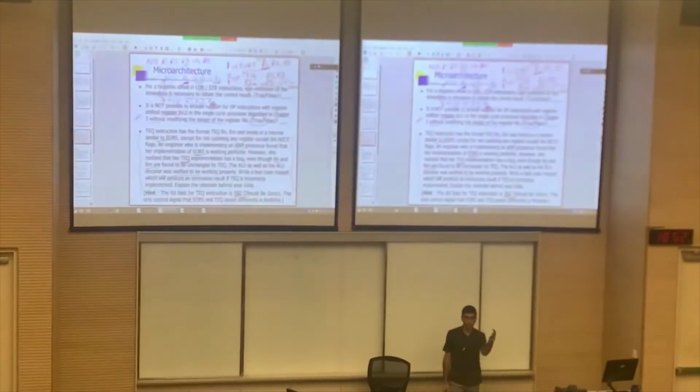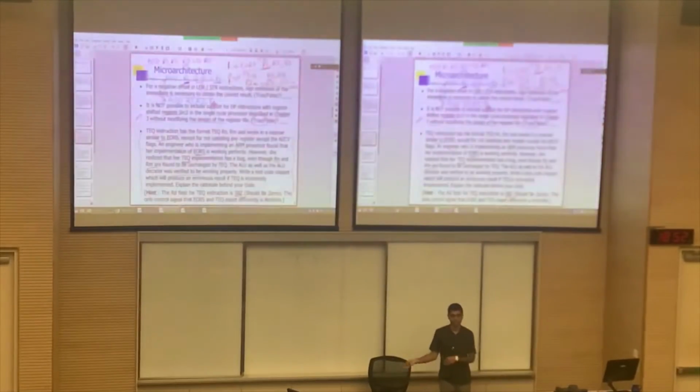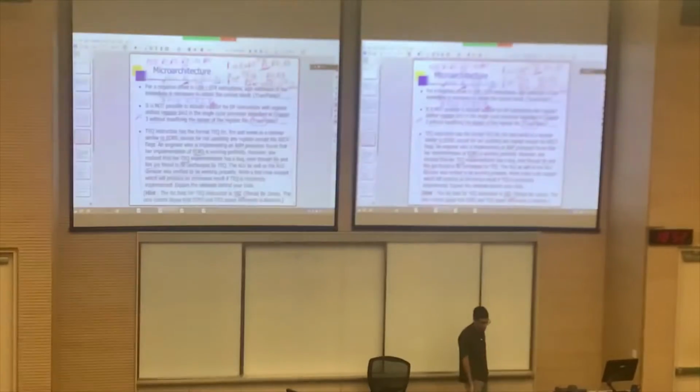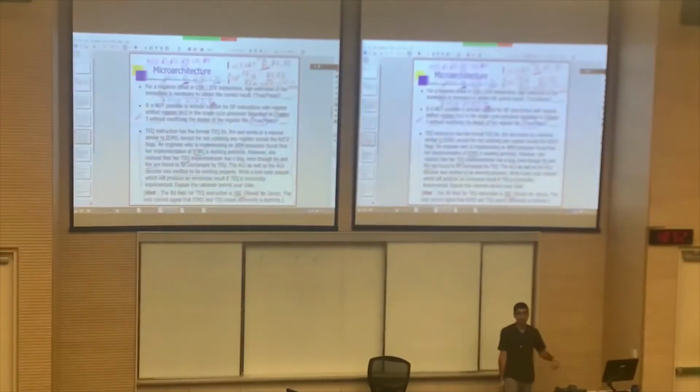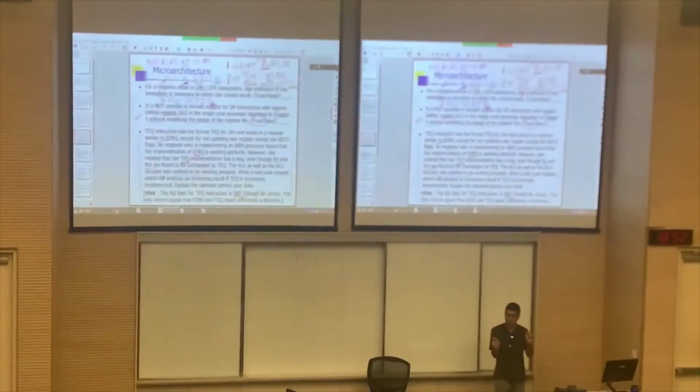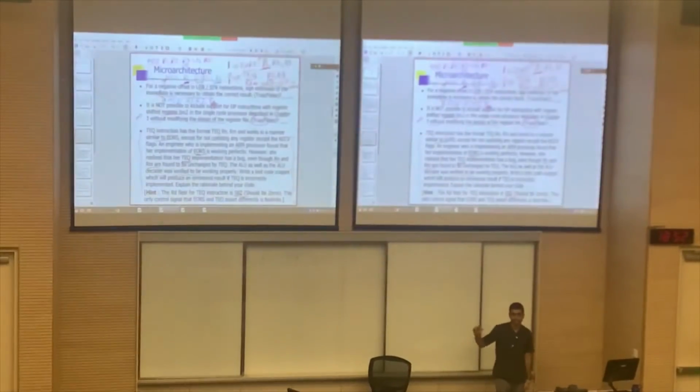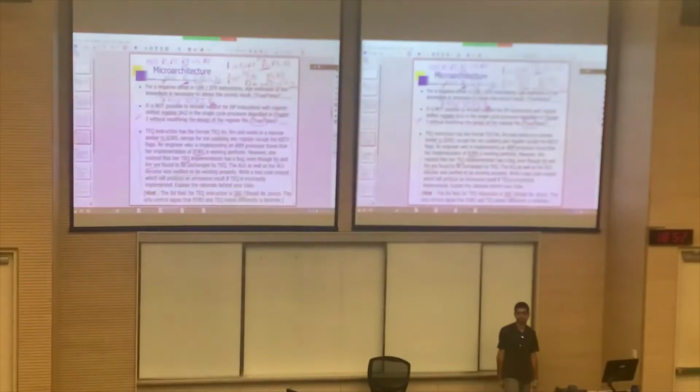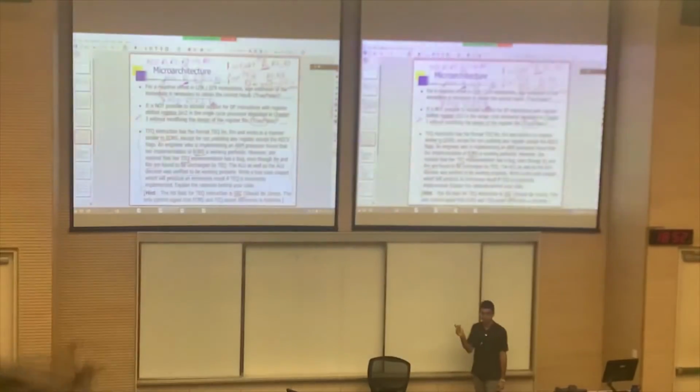And some of you had already experienced that. Some of you came to realize that there was a mistake later on. Some of you probably did not even realize because you did not use R0 after that. If there is any instruction that makes use of R0 after this TEQ, you will see that the value of R0 has now been erroneously modified, inadvertently modified.